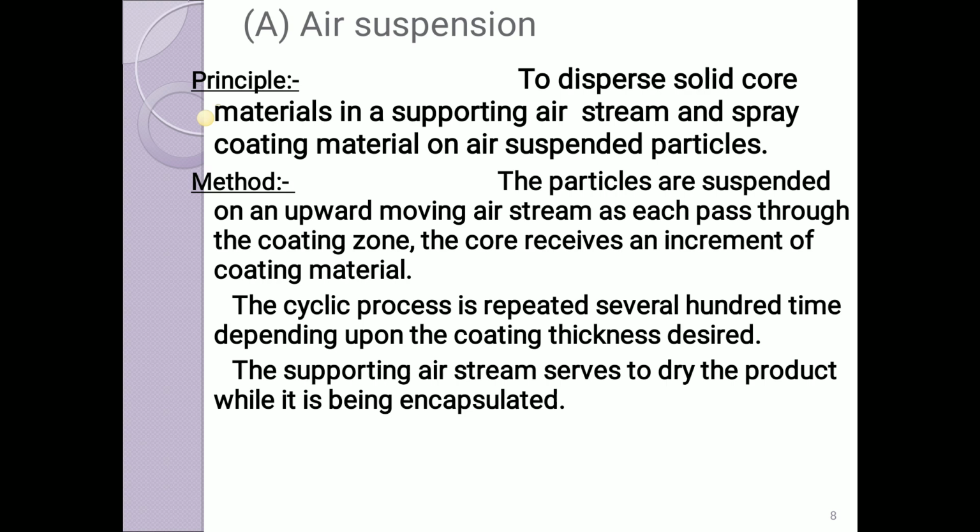The method is that particles are suspended in the upward moving airstream. As each passes through the coating zone, the core receives an increment of the coating material. So as the material passes from one side to another, it receives the coating material on the surface, coated on the solid particle or on a liquid particle.